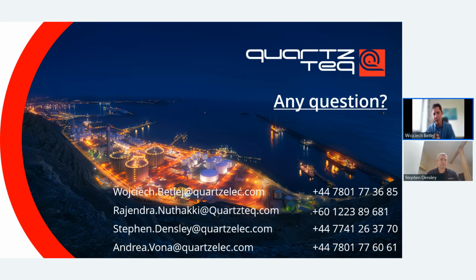So every year during your annual inspection, you would perform offline PD. If you see a visual problem, or any change in PD value, I think this is the moment when you really should start considering installation of a permanent online monitoring system. Ideally, you should have it from the very beginning, but if you don't want to do it, try to measure it every 12 months. And then when you see a problem developing, go for an online system.